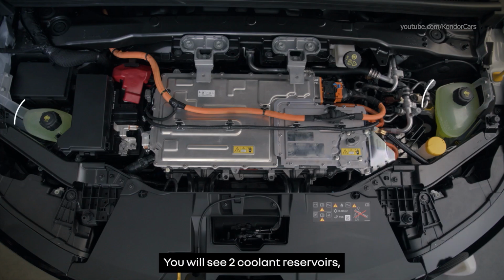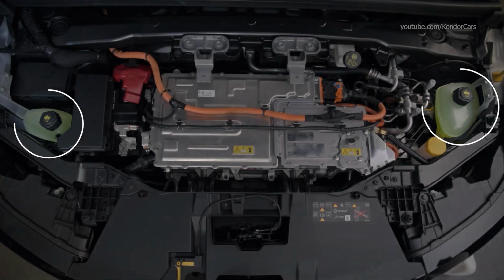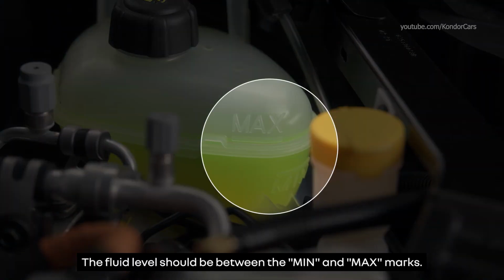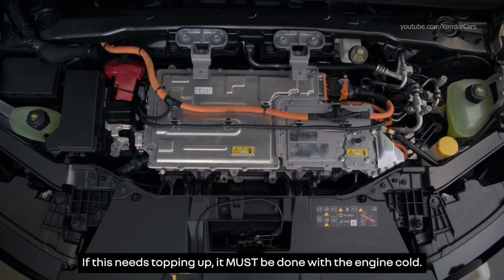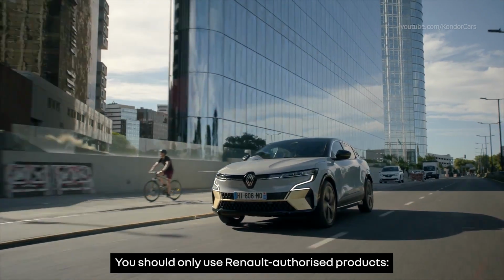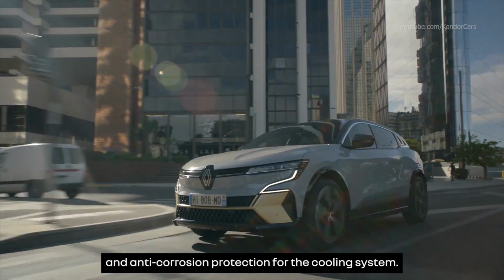You will see two coolant reservoirs, one for cooling the electric motor, the other for cooling the traction battery. The fluid level should be between the min and max marks. If this needs topping up, it must be done with the engine cold. You should only use Renault authorized products. They provide your electric motor with anti-freeze protection and anti-corrosion protection for the cooling system.